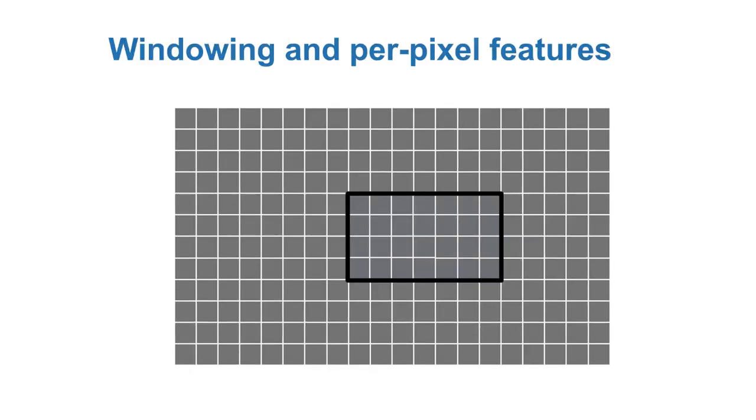In CMOS cameras, it is often possible to already, when communicating with the sensor, request only a subset of the image, as only the subset of the pixels can be told to transmit their information. This can reduce communication requirements. However, more importantly, CMOS sensors can be designed to have specific features built into the electronics of each pixel, tailoring the output to the needs of the application, and reducing the need for external processing.